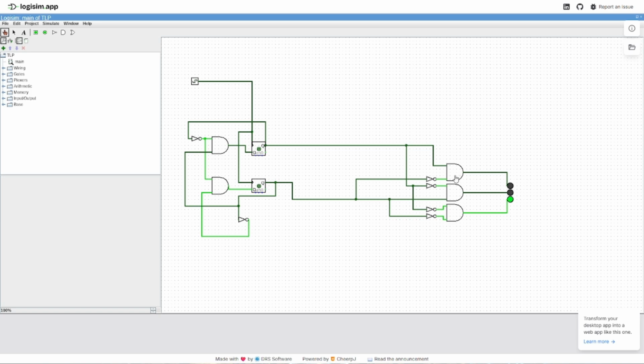The first AND and the second AND have only one NOT and the other one is pure on both ANDs, except the last AND, which is for the green light, having two NOTs for both outputs of the D flip-flops. So it will be 1 and 1 into the AND gate, and the output is 1 to the green light.